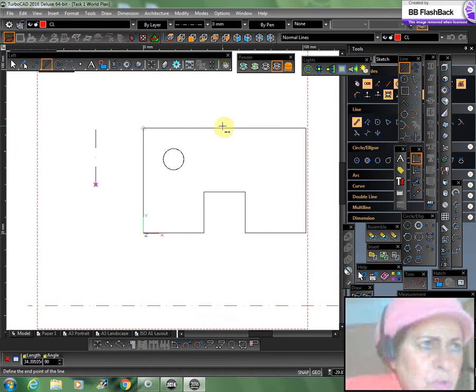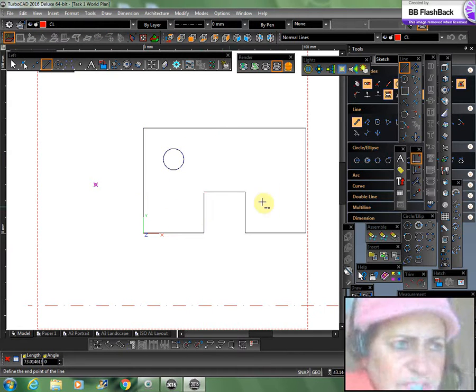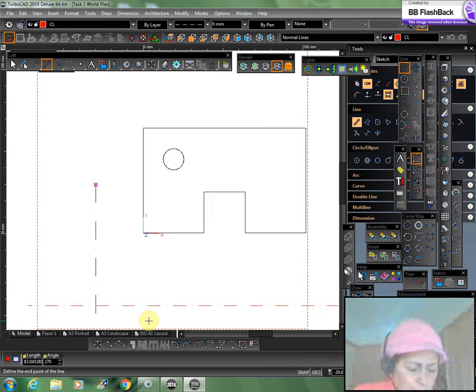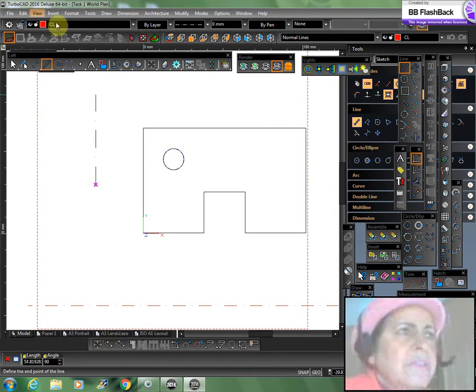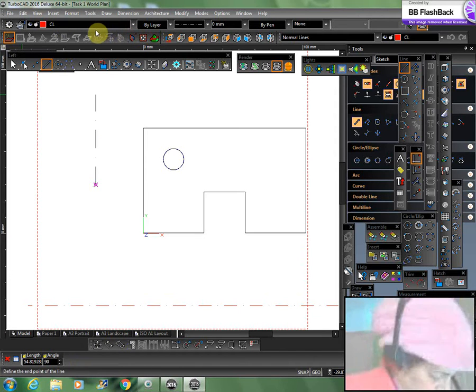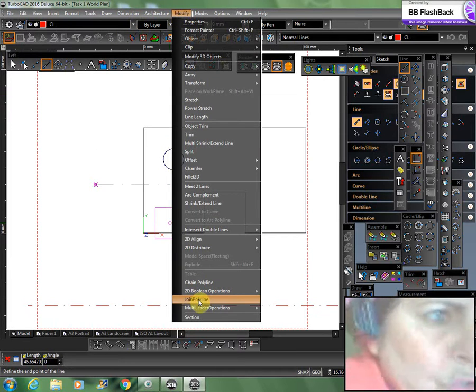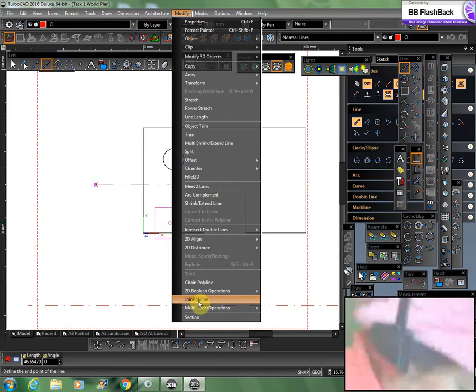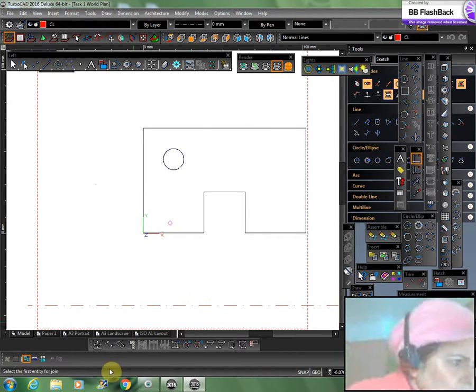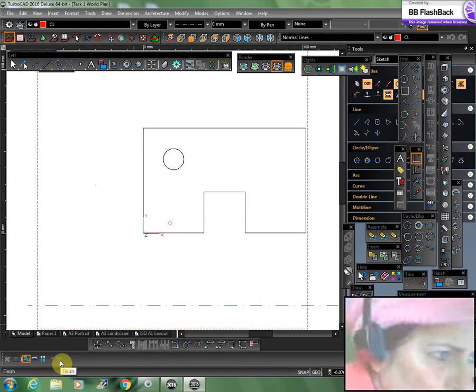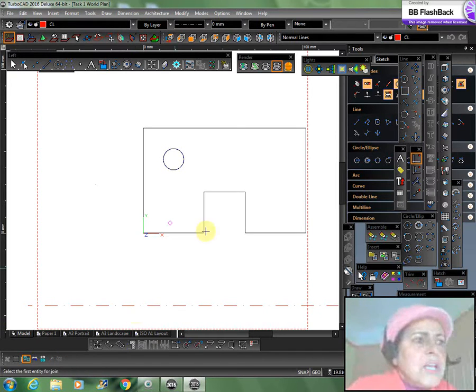then I have to also click on all these edges on these sides of this shape to choose the object, and then at the bottom, when I click Modify and I click Join Polyline, there is a flag with black and white, and when you put your cursor on it, the word Finish comes. Click on Finish, so there will be a polyline created